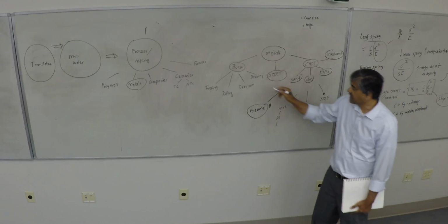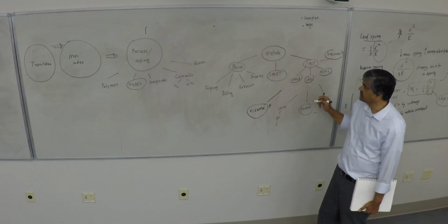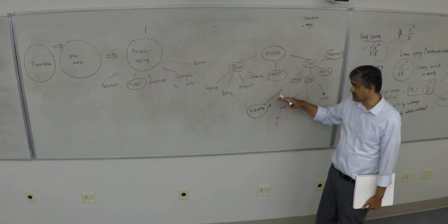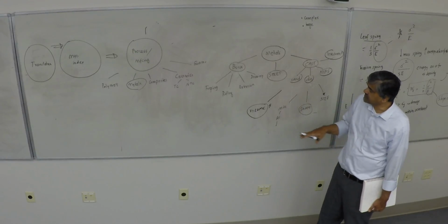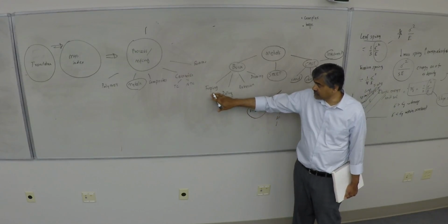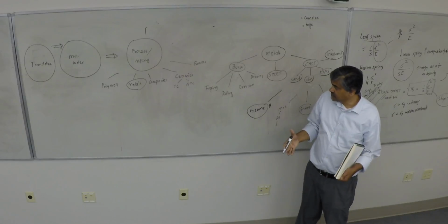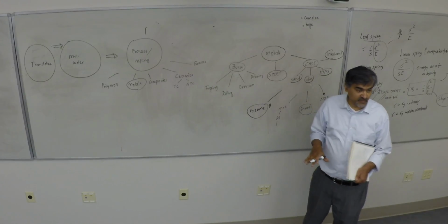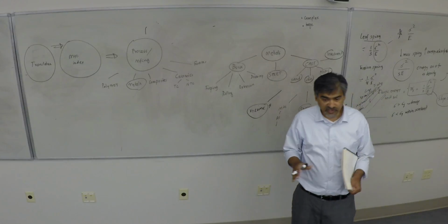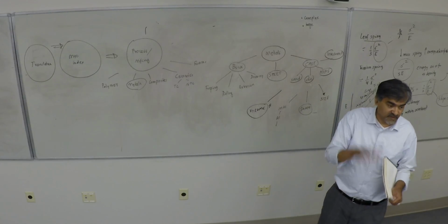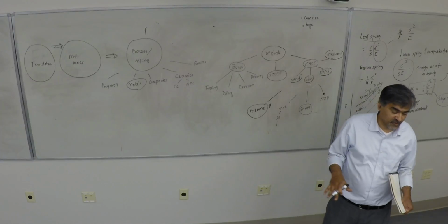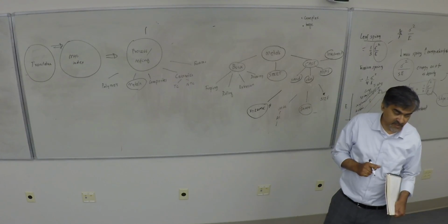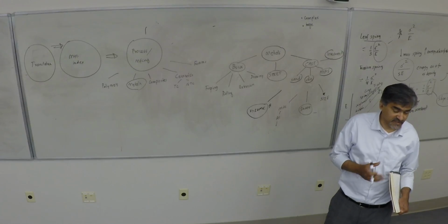So on the metal side, of course I can spend 2-3 days just talking about each process, but in a very basic sense, forging, to remember everyone, is the three-dimensional charge part, which is then a deformation process. No volume is gained or lost. You just take a bulk and brute force take it from one shape to the next shape, like crankshafts and connecting rods and railroad ties and things like that.